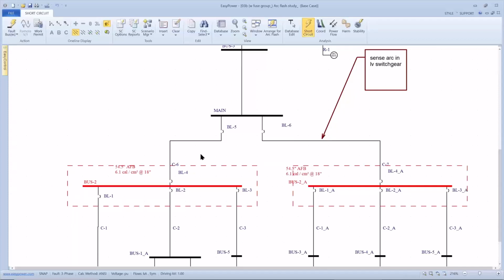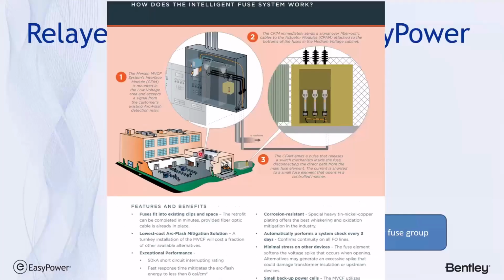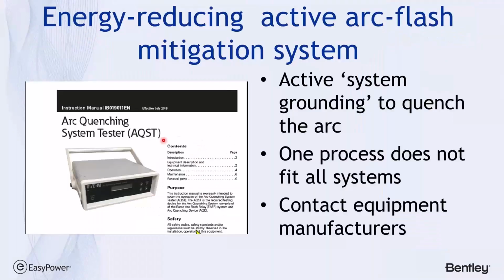All right, so another similar device that's been developed is quenching relays. And this operates very similarly in that they detect an arc on the switchgear and they automatically ground the bus, or whichever bus is being faulted, and it makes the upstream protective devices trip instantaneously, which if they were fuses could be a half cycle result.